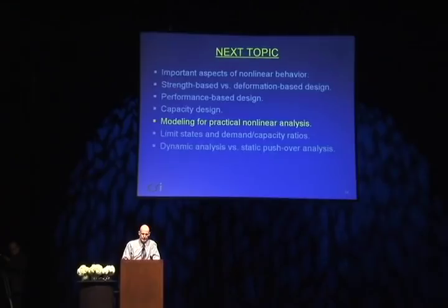The advantage, though, of using nonlinear analysis is it can be more accurate. It can give you more accurate deformation and strength demands. Judgment or simple analysis can lead to over-design, and if the judgment is faulty, it could lead to under-design. And nonlinear behavior is pretty tricky. If you're not going to use analysis, it does require some pretty good judgment.